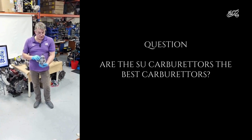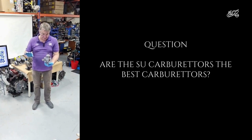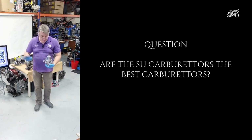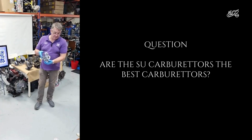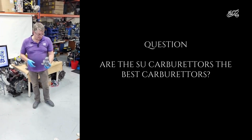And most of the cars that went to the US, they stopped using SUs and they went to the Strombergs, because the Strombergs could be set and stabilized more reliably. So once you set up a Stromberg, they actually sealed the adjustment screws, and as long as you didn't touch it, it would stay where it was. So SUs need a little bit more tinkering, but they're ultimately pretty bomb-proof, right? And that's what makes them the favourite.